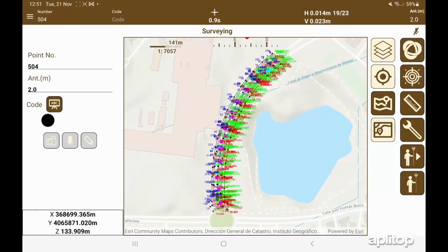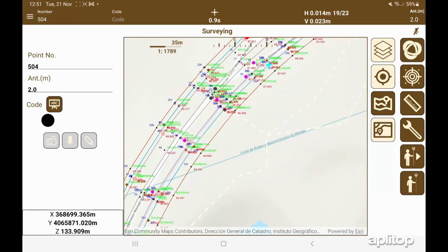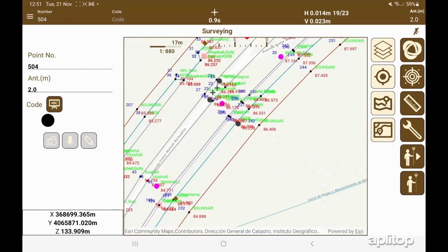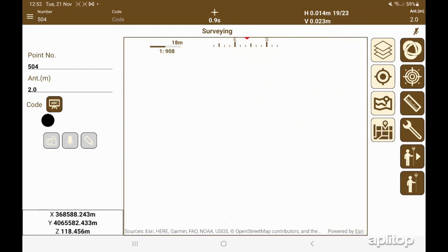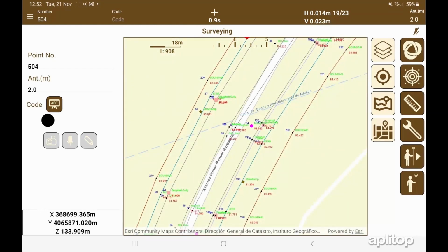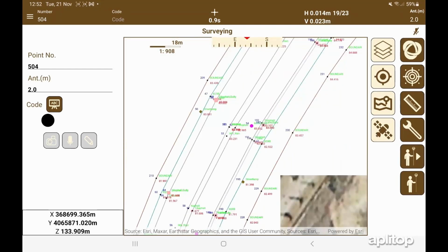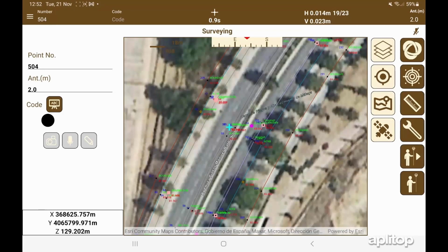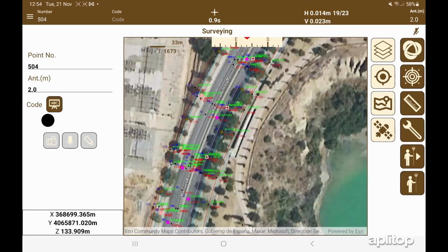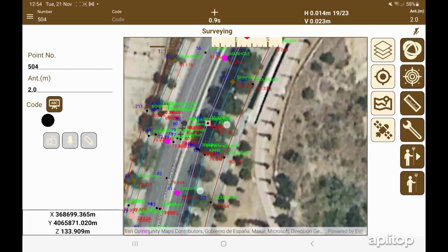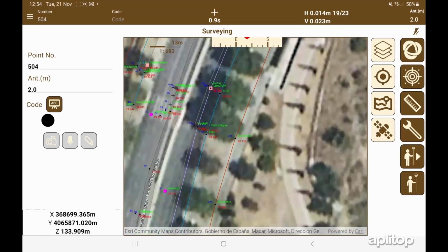This video will show you how to create an on-premises system. To do this, we start from an example in which a topographic survey has been carried out using RTK using a reference base with coordinates on the fly. For this reason, it is observed that there is a certain displacement between the data taken in the satellite map. The red lines do not coincide with the end of the pavement.